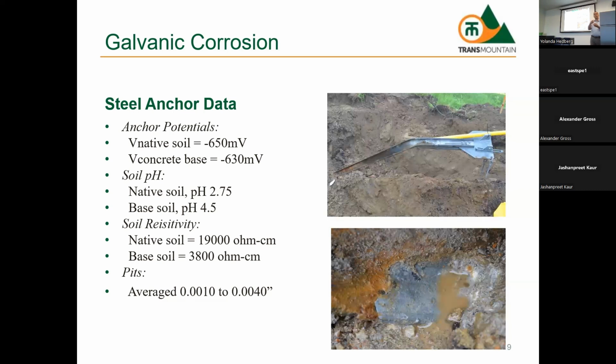Galvanic corrosion due to the couple of the copper, which was connected to the galvanized structure, steel. And going back two slides ago, I told you to remember that driving voltage number of what? 0.3 volts. So that's copper to galvanized steel. Which one, steel or copper, is anodic? Steel. Okay. Steel is anodic to copper.